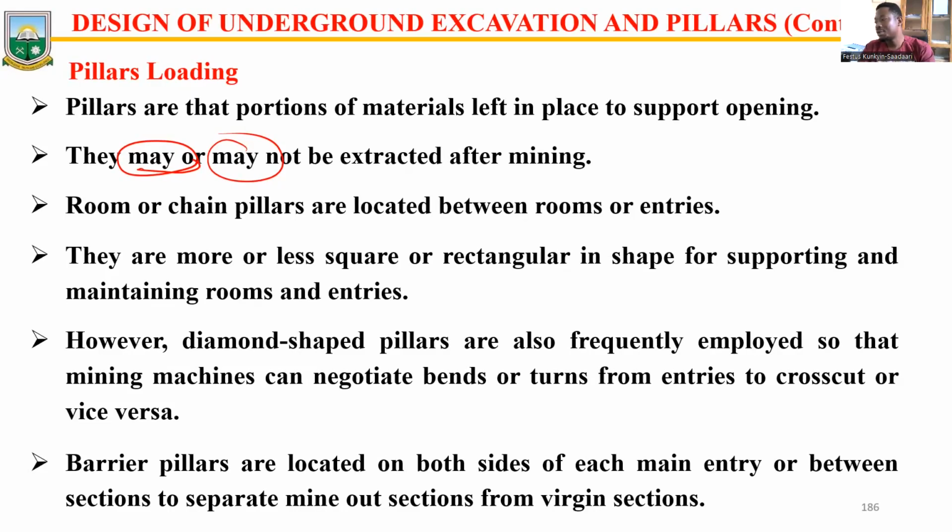All right. Any other contributions? When can we mine out the place when we want to practice the refilling method? Okay. If we want to practice refilling, we can go for our pillars and then bring in foreign materials and use that to enhance the stability.